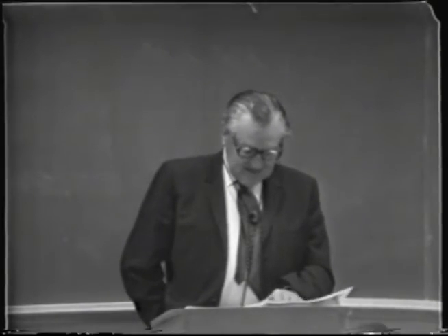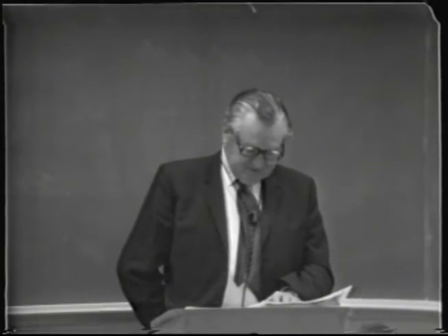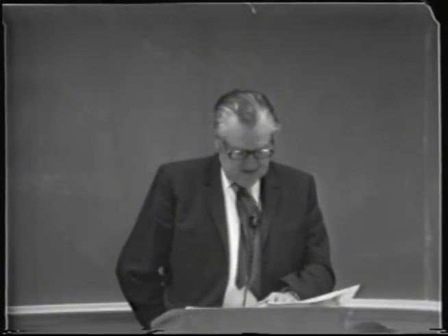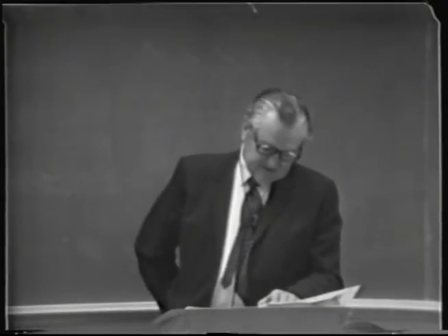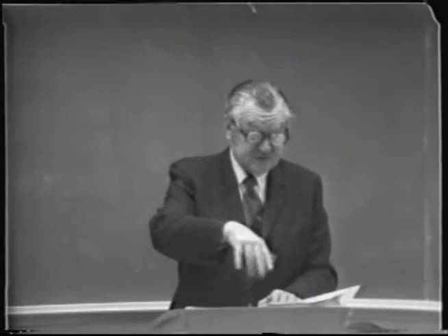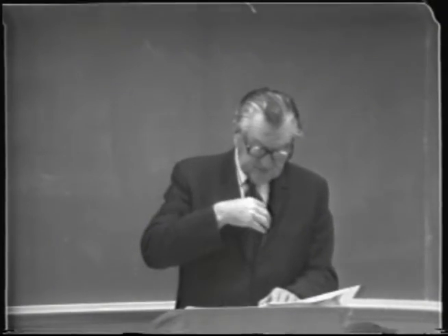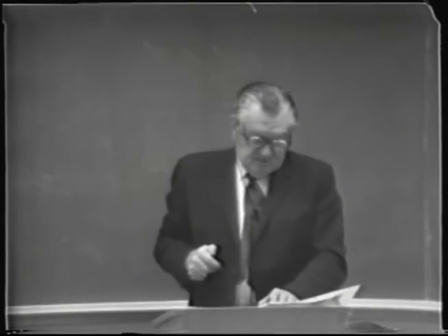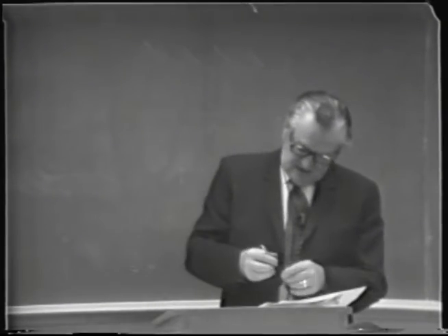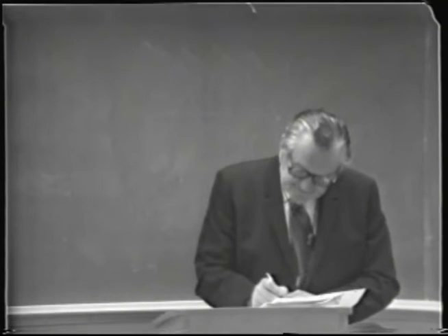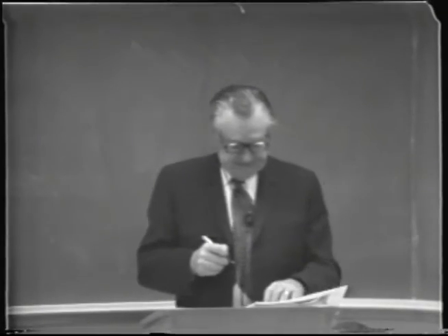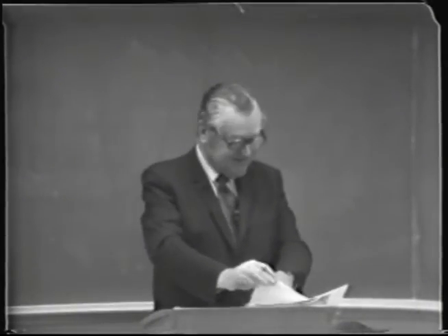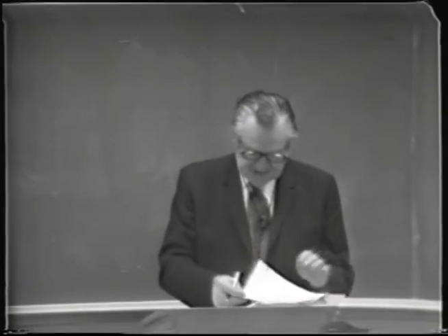Now, it shows here the entrainment ratio, pounds of entrained vapor per pound of live steam. If this recompressed vapor is going to be applied at 18 pounds per square inch, and it's only been drawn off at 15, it only has to be compressed 3 pounds per square inch to get an entrainment ratio of 3.33 per pound of live steam. Actually, that amount of live steam saved in percent is an incorrect value there, because I checked it out myself. It's a typographical error, because that should be 77%.